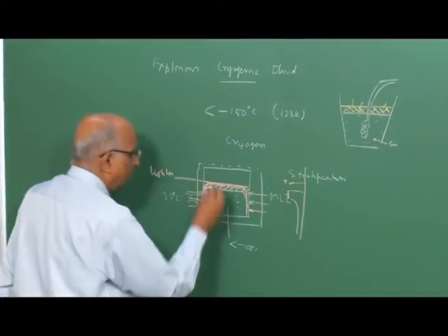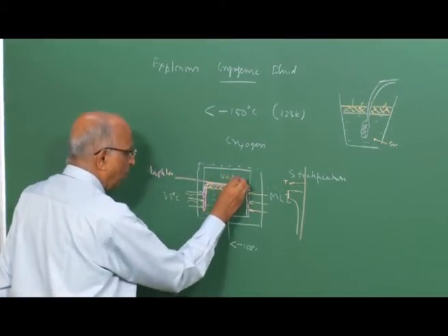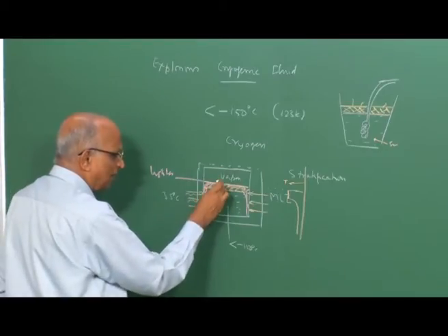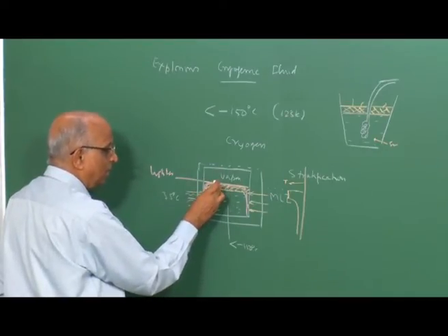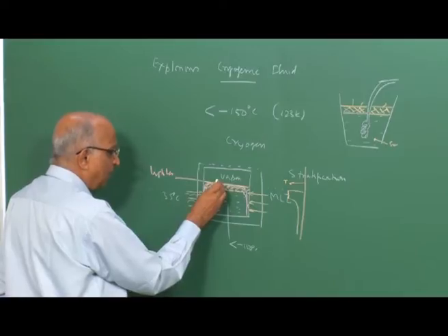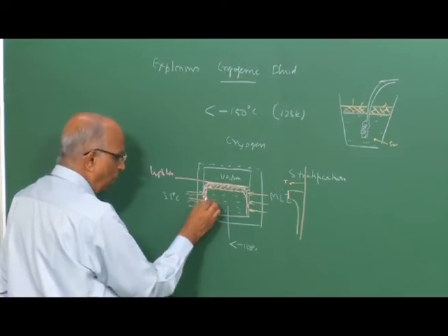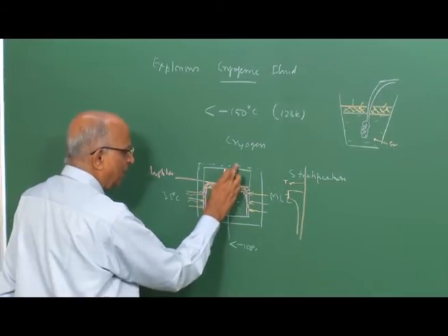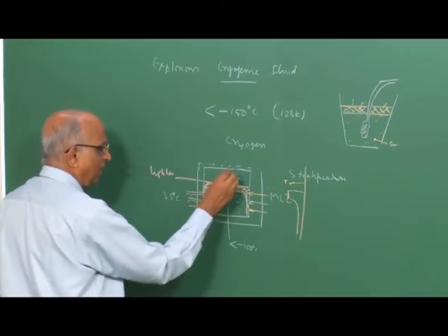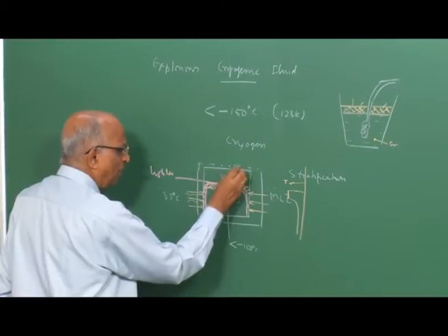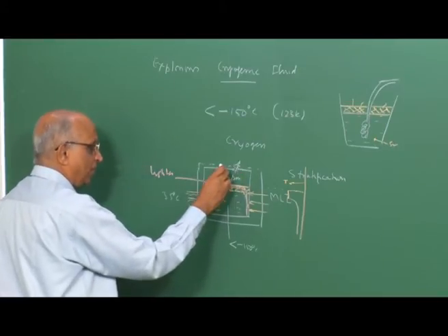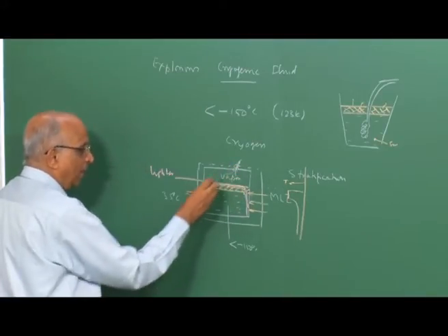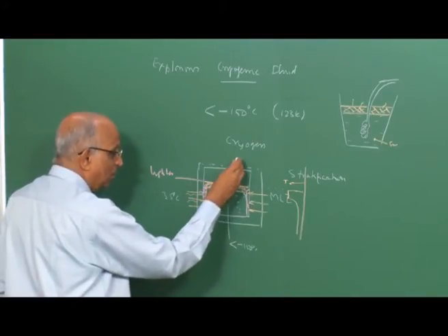The gas, that is the vapor of this particular cryogen which is on top, is also warm at this particular temperature. It tends to be in equilibrium, and if more and more warmer fluid comes over here, gas is generated. Therefore, in all cryogenic appliances, you give something like a vent valve through which, if the pressure increases, the vapor gets released through this particular vent.